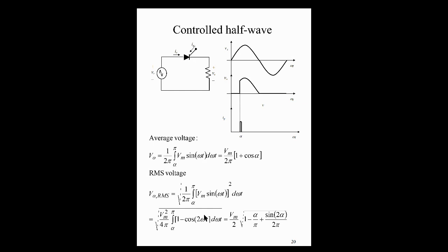We then look at the case where we have resistive and inductive type load, and we saw where there was a phase shift, very much different from when we have a purely resistive type load. We observe a difference in the current and the voltage waveform. And also, when the current goes to zero in the diode, we have that cutoff angle beta that is associated with this kind of circuit.